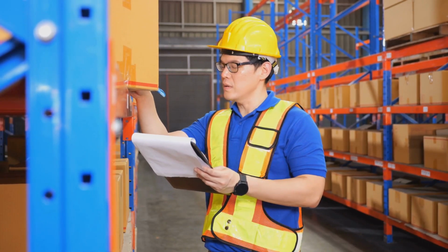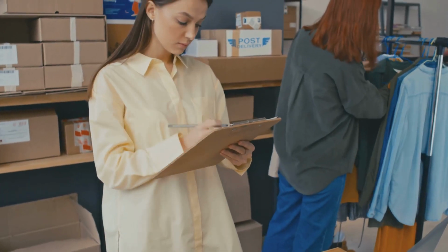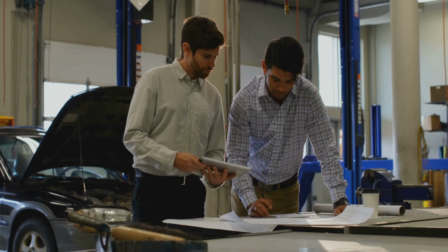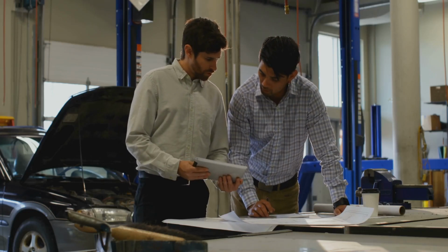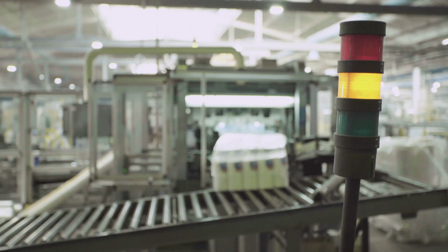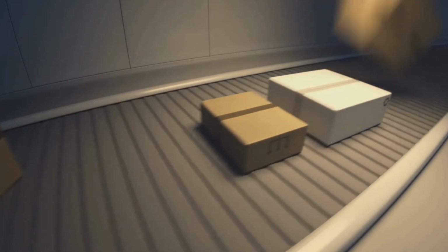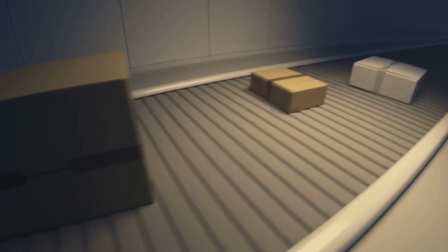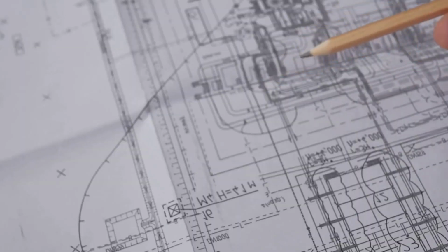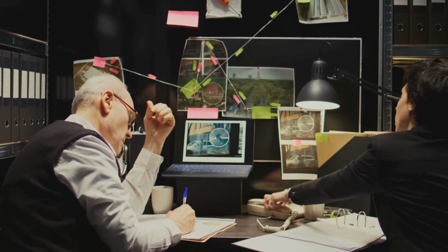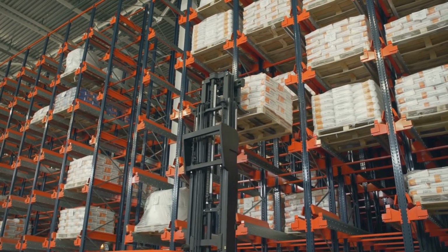Target the biggest chunks of non-value added time, like that 4-hour wait. Ask, how can we make the process flow continuously? Maybe move stations closer, or use a conveyor for one-piece flow. Try a pull system. Let the last step pull from the previous one, preventing overproduction. Draw these ideas on your future state map. The new map shows a leaner process with less inventory and shorter lead times.